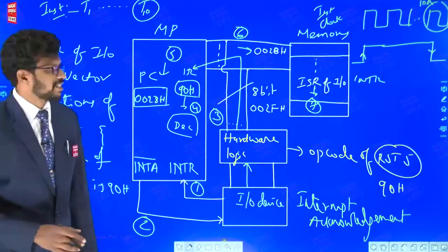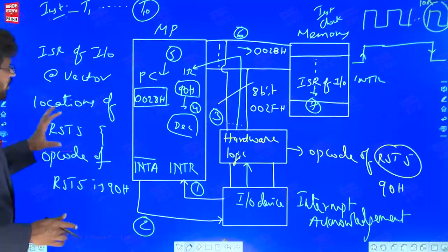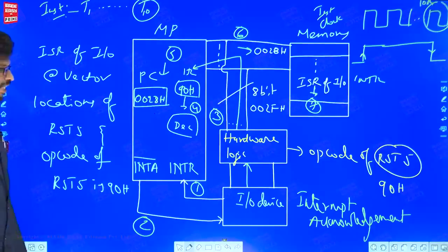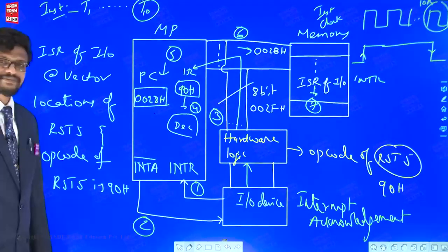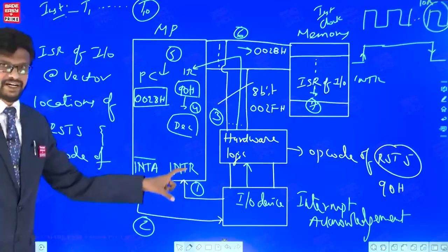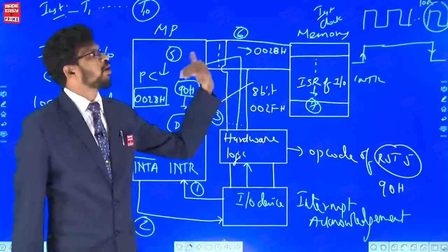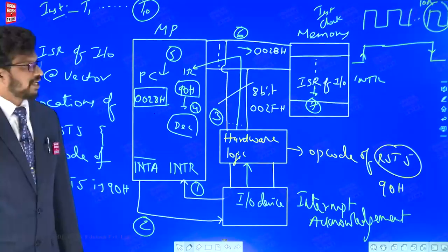So we can understand some questions which are possible with these interrupts. Now observe, hope that you have understood this. So tell me, why is INTR called non-vectored? Because there is no specific address location for INTR. Whichever software interrupt you select for storing the program, only at that particular location can it move.